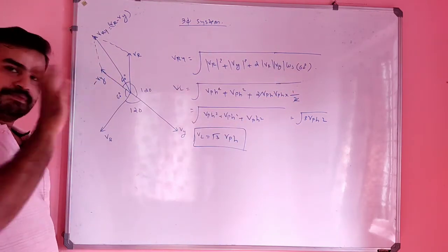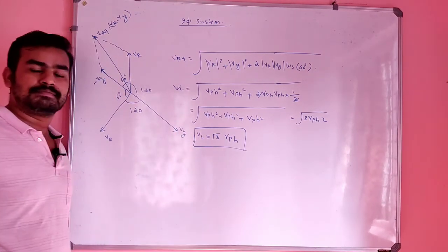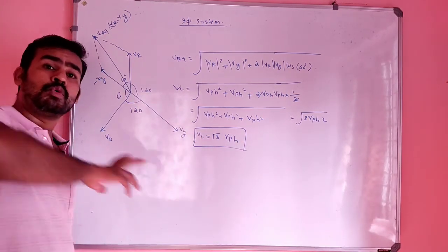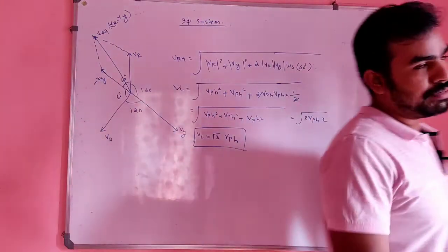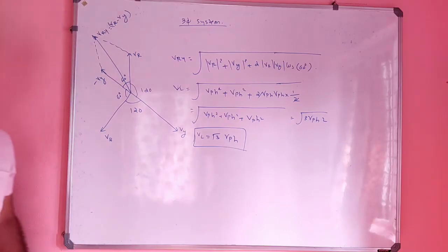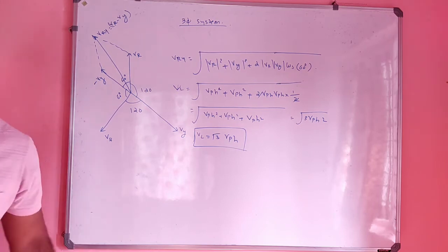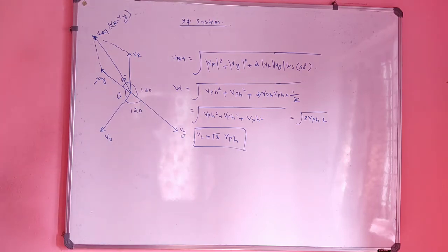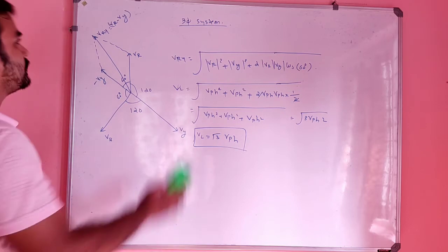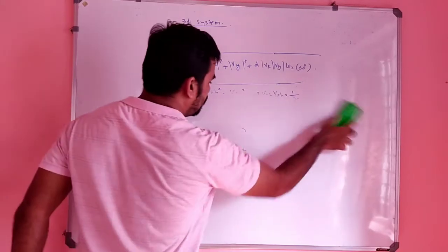We already learned that there is some difference between line voltage and phase voltage, right? So what is the difference? This is the difference. The line voltage will be root 3 times higher than that of the phase voltage, beta. It is 1.73, right? So that much times higher than the phase voltage is the line voltage. Is it okay with you? The concept is clear to you, beta. Okay. So that is the concept of star connection.